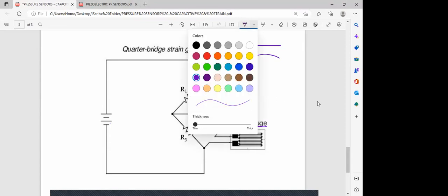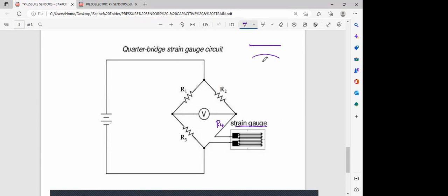So now I'm going to indicate that rubber band. At one time it was like that. Now the rubber band has become like this. That stainless steel rod is putting a pressure on this strain gauge. This strain gauge is a metal wire that is now becoming like this. So one time that strain gauge was like this. Another time the strain gauge is like this. So the cross-sectional area has become less over here.